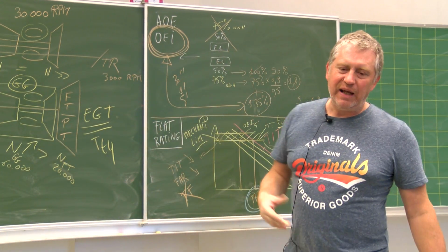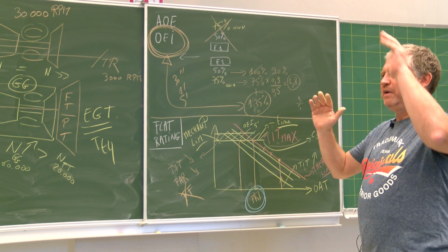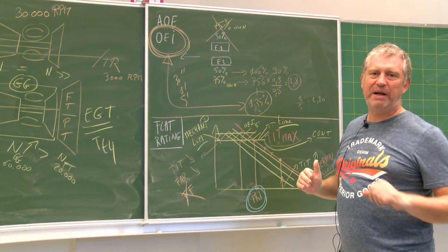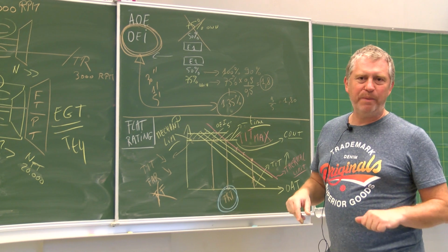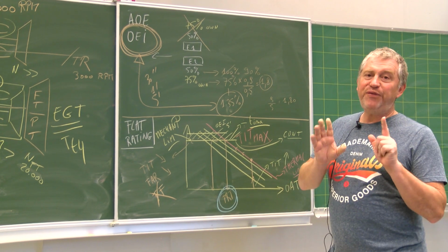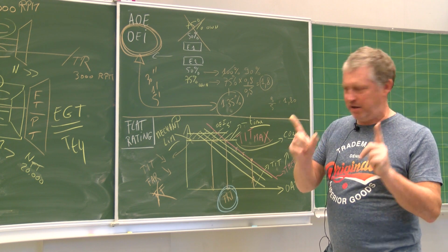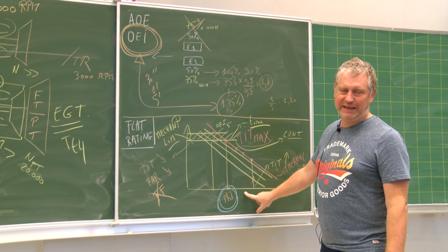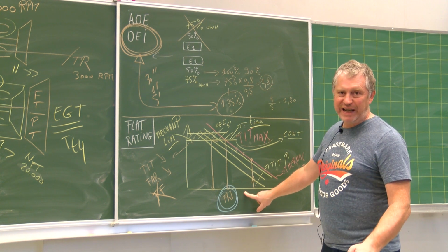Then you land and you take 3 other persons, you do the same, you take off, and you will take off with an EGT limit that is higher and a torque limit that is higher. Not a problem. You land, you take other 2 persons, and what's happening at that time? If you are in the summer, you are on the right-hand side of the flat rating temperature. And when trying to take off with these